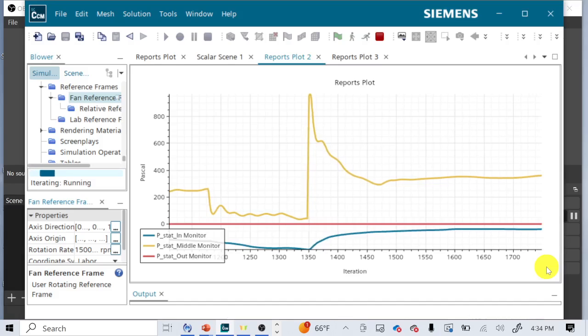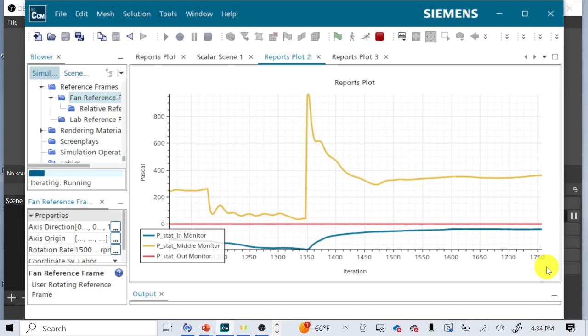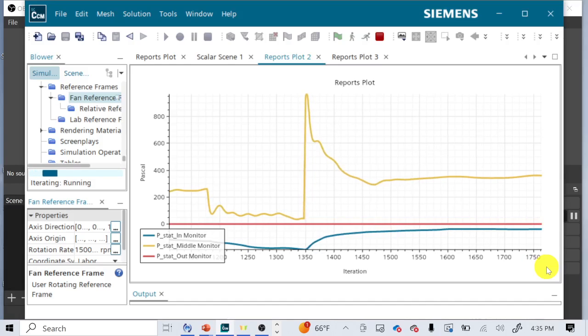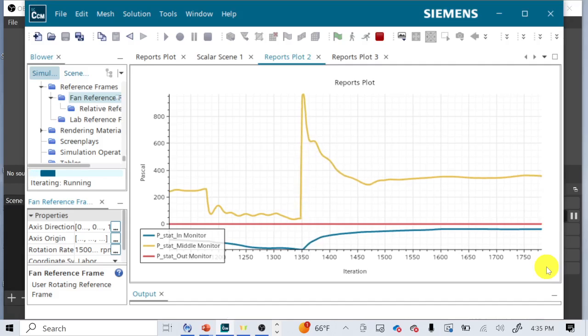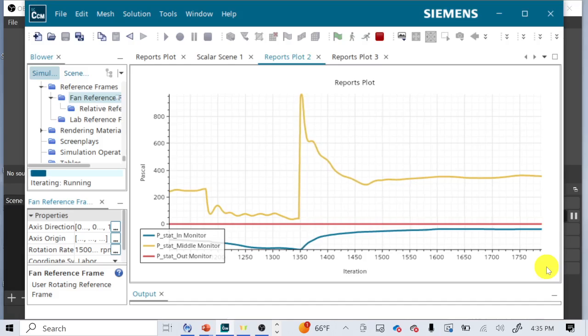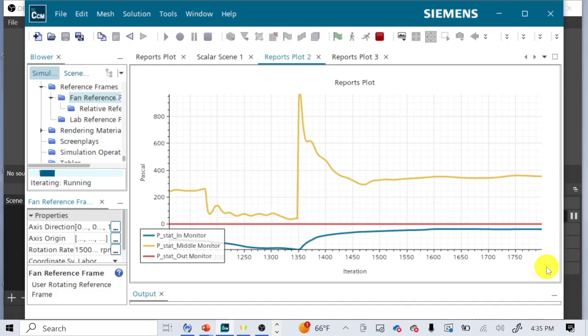Potentially, yeah. Now this is probably pretty thoroughly incompressible, so it's probably not going to change by much, but it conceivably could. It's something to look at. Or maybe that validates that this is incompressible flow. Theoretically, if this was a full-on compressor and not a blower-style fan, then yeah, it would change temperature. Generally, if you run air through a compressor, it does get noticeably warmer.